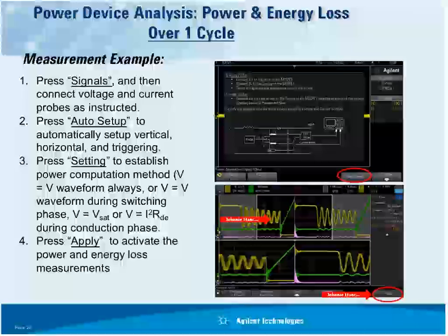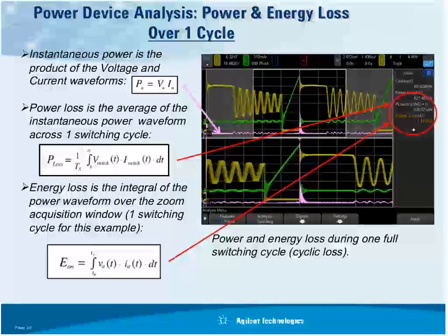Now let's take a little bit closer look at some of these waveforms. Again, between this point and this point is when current is flowing and voltage is very low, near zero. And I just want to highlight a problem that we have here. This voltage waveform is typically a very high voltage waveform. In the case of this power supply I'm testing, I think it was in the range of something like 40 volts, but it could be in the range of hundreds of volts.